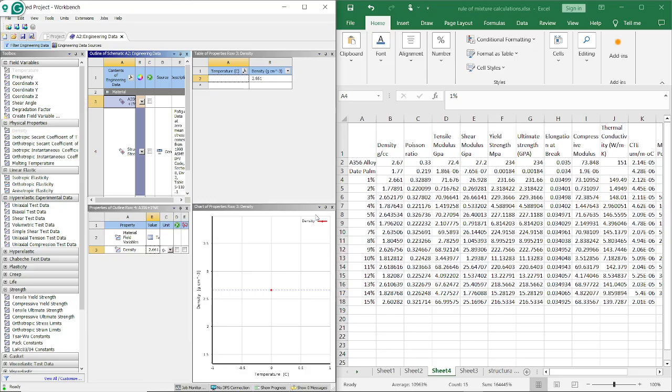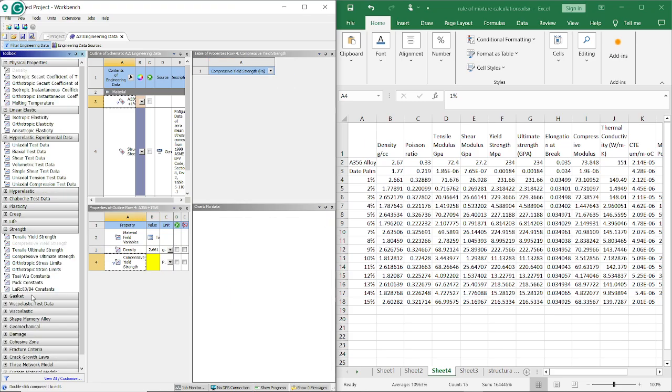This time we will need to put Poisson ratio. Poisson ratio can be automatically calculated actually. If you have the tensile modulus and the shear modulus, you can calculate Poisson ratio. So that means you need tensile compressive strength, bring it there or double click. You need tensile yield strength. The same thing for a brittle material, they are the same thing, right? So compressive strength, what else do we need?